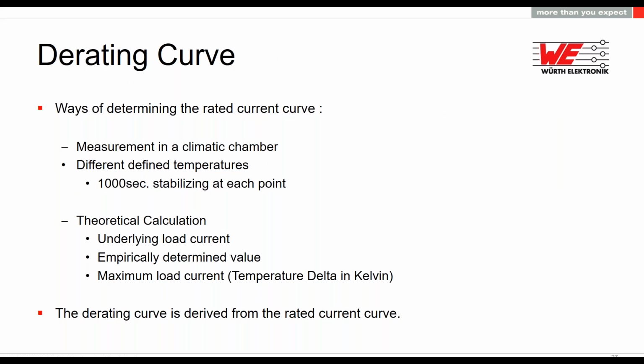We also could do a theoretical calculation if we have the correct basic load current, some empirical values, and if you know the maximum load current. There is also a table in Excel showing how to calculate this for some connectors. Our field applications engineers have access to that, so you can contact them if you need it for a certain connector. And out of these results, we can create this derating curve.